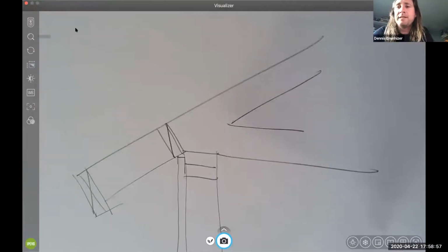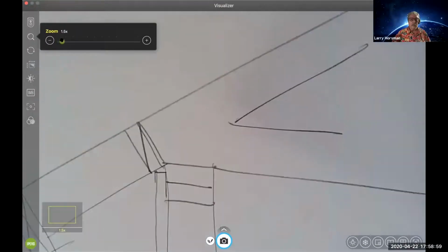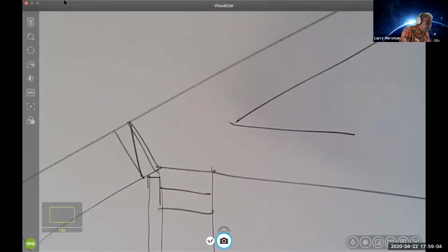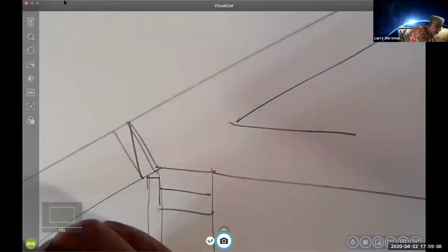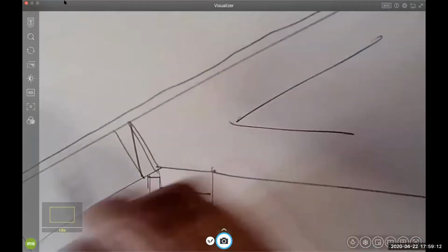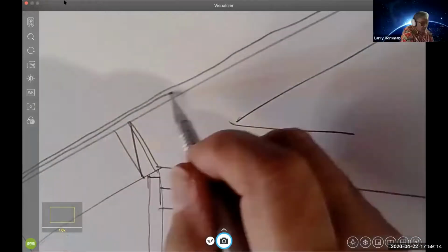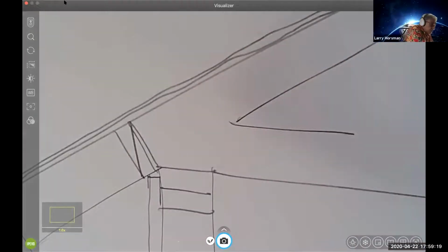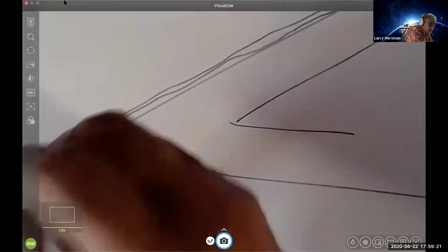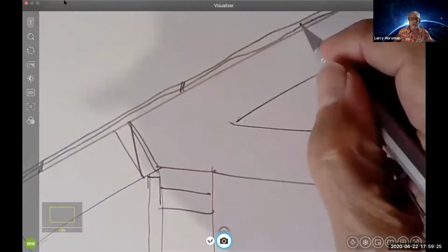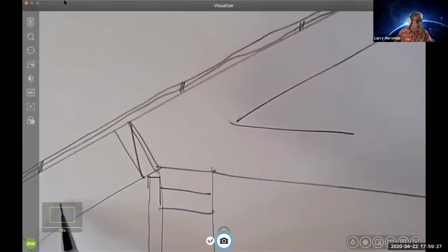Okay. Well, won't that make a bad shear transfer detail though? Well, it is or it isn't. For shear transfer, I can do a number of things, right? And that's something else we have some problems with, because if you're in a very high fire hazard zone, you can't have this 2x framing sticking out here beyond the wall.